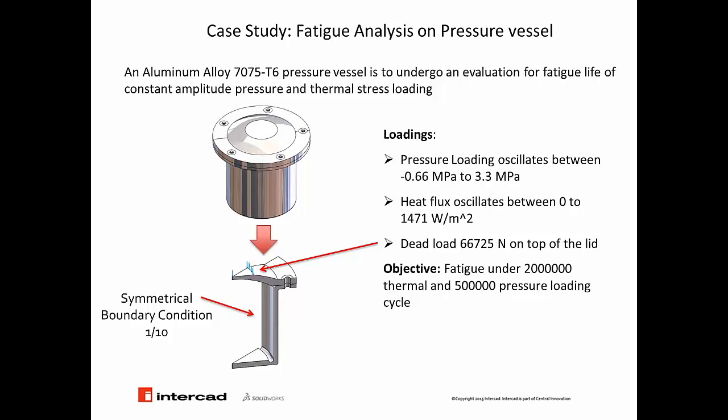We introduced the loading history with constant amplitude or variable amplitude, and mentioned that the case study we will take today is just a constant amplitude. We introduced the SN curves and also the effect of mean stress and the interpolation data scheme.